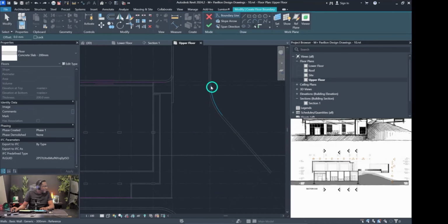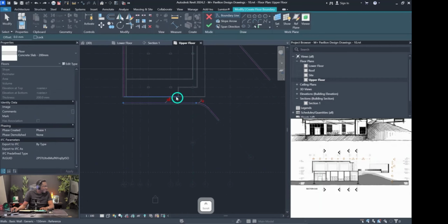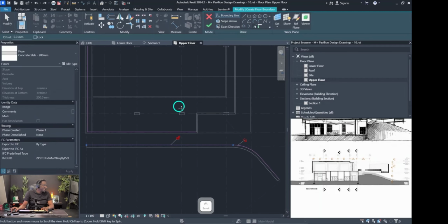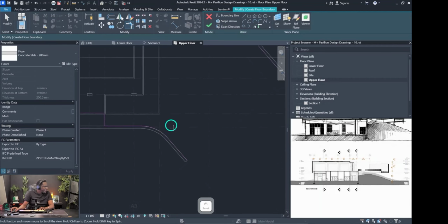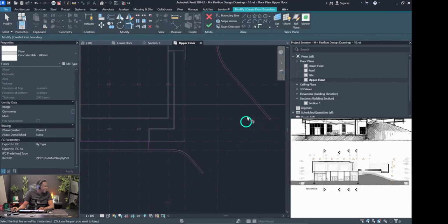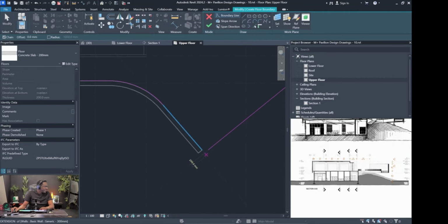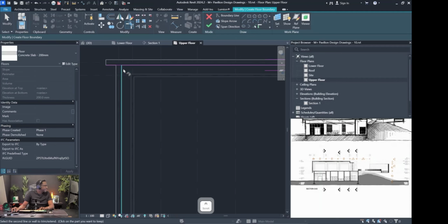All right, now we also have a floor slab that's going to be out here. So I'm going to pick these as well. It's going to come somewhere here and then come over like that. Okay, so pick lines will only get us so far. Now we need to go to our line tool. So this floor slab will probably come out like that, and we're going to use the trim tool to trim that up. Or line tool here, and then trim tool. All right, then we need one across here. We need to make sure these touch, so that up. All right, and trim this up.